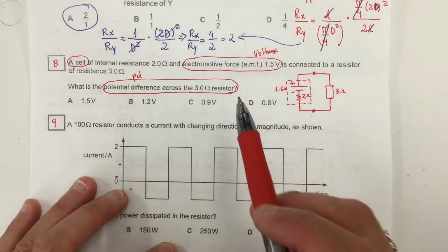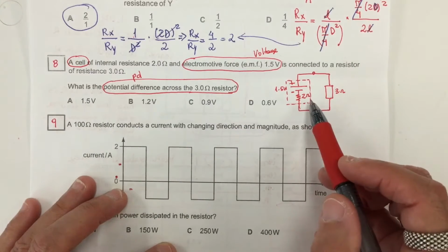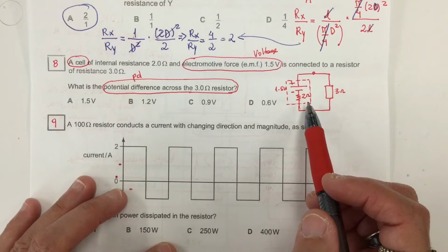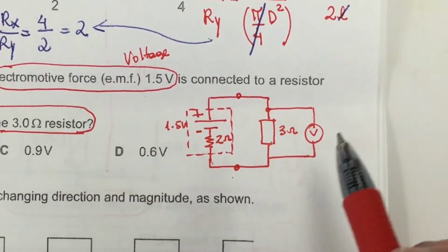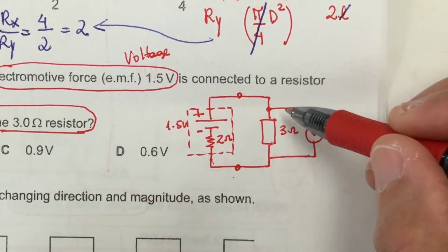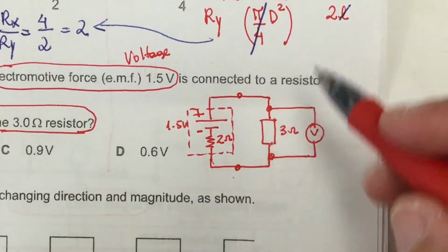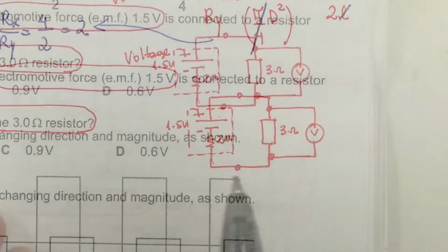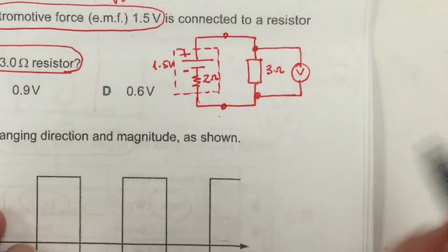One alternative and very quick way to do this, when you have two resistors in series in a circuit and one battery providing energy to both, is using the formula for potential divider. So potential divider is very simple. It's just like if you have a voltmeter with the terminals connected to the terminals of this resistor, and you want to read the voltage across this resistor. The formula for potential divider does not include current, which is a great advantage.